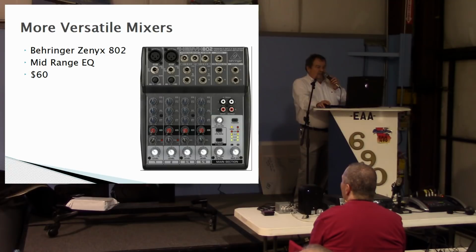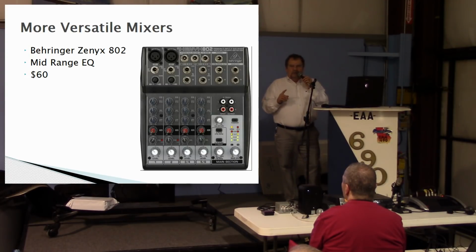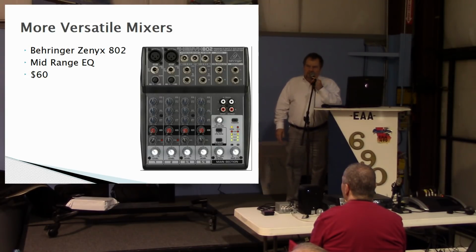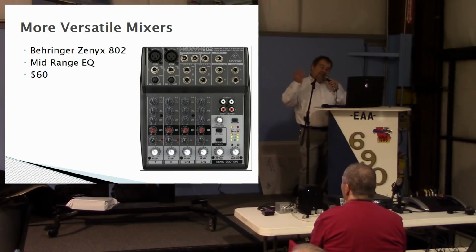It's got neat little level meters here, so you can actually see, unlike most radios. Now, on sideband radios, we can see deflection in ALC, and that's great. One big beef I've always had is that on FM radios, you have no idea what your audio level really is. You know, old cheap Radio Shack tape recorders used to have a peak light, so you could tell if you were talking loud enough or too loud. I don't know why they don't put those on FM radios, because you hear folks talking like this, going down the road noise, and some people are like this, and it just doesn't matter. So anyway, pet peeve of mine.